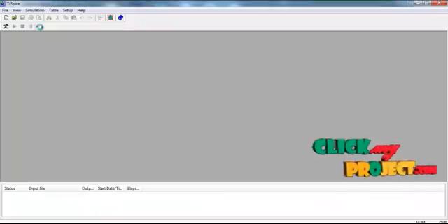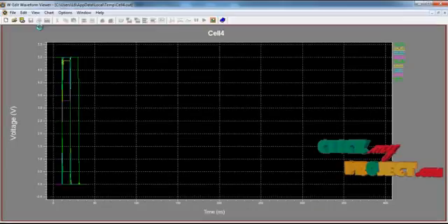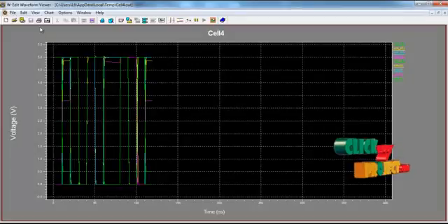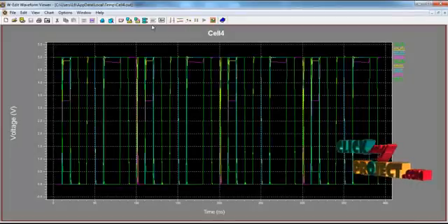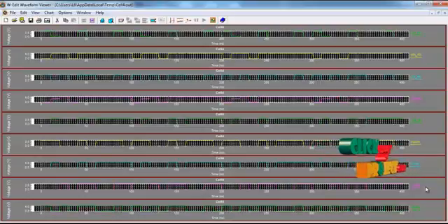This output produces the T-Spice and the W-Edit waveform files. T-Spice is the background running process, and the W-Edit waveform file produces the output variations for voltage level. We apply three input data bits, the carry, and A, B inputs passing into every adder circuit, and the carry passes to the next input carry. The first 3-bit sum and carry output, the carry output is passed to the next 3 input adder structure. This passes to the overall final output. These are the sum and carry outputs for the overall 8-bit adder circuit diagram.